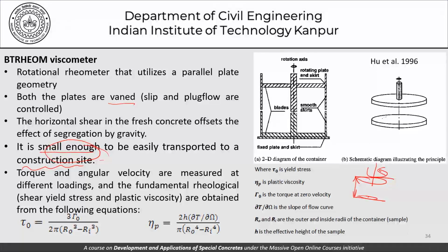So the idea of all this discussion today was to introduce to you this very important, very interesting field of rheometry, where we study the deformation of paste, mortar, or concrete, and try to study the flow characteristics in an effort to better understand the segregation, flowability, viscosity, and so on for fresh concrete.